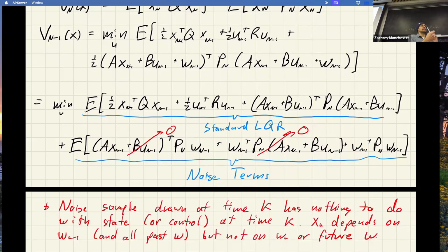Because of linearity, changing the sample rate on the noise just means you're letting the noise integrate for longer, or average out for longer. So what you would do is just scale the covariance of W by some amount proportional to the sampling. You can pick your sample rate here and it doesn't change anything. It just changes the covariance on the W.